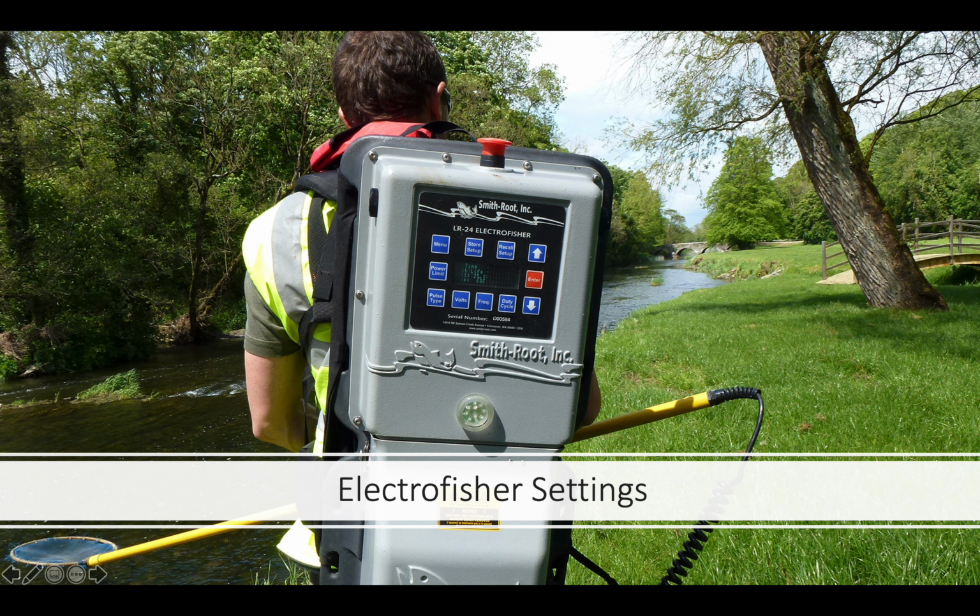In this section, I'm going to go over the Electrofisher settings. You can see here what the control panel of the Backpack Electrofisher looks like. There are different buttons. You can go through the menu, and you can set the pulse type, volts, frequency, and duty cycle. These 4 components are what we're going to be going over in this section.